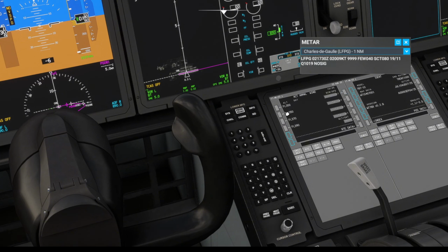And then usually I would take flight level 200. This just gives us a reference in case of an engine failure. This could be an altitude where we basically dive down to, so it gives us like a middle altitude between 390 and 0, just for reference. So this is also really a lot of work if you have to put it in all by yourself. I'm gonna remove this for a second.